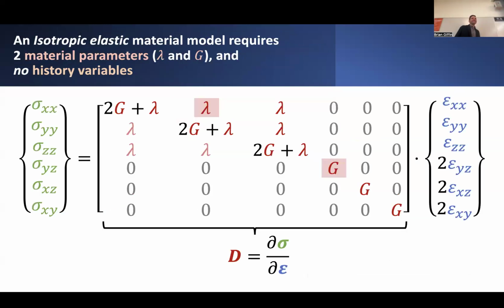So obviously, we'll start with some of the simplest examples of material models that you're already familiar with, just as a baseline to frame your viewpoint and your state of reference. Isotropic elasticity. This is effectively what we've been talking about up to now, almost exclusively. We've referred to material behavior in this way, which says that there is this assumed linear relationship between all the different components of stress in the material and the resulting strain components in the material. So we were able to parameterize this relationship in terms of two material parameters, or two material properties corresponding to the elastic coefficients. You could parameterize that in terms of Young's modulus and Poisson's ratio, or you could do it in terms of shear modulus and the Lamé parameter.